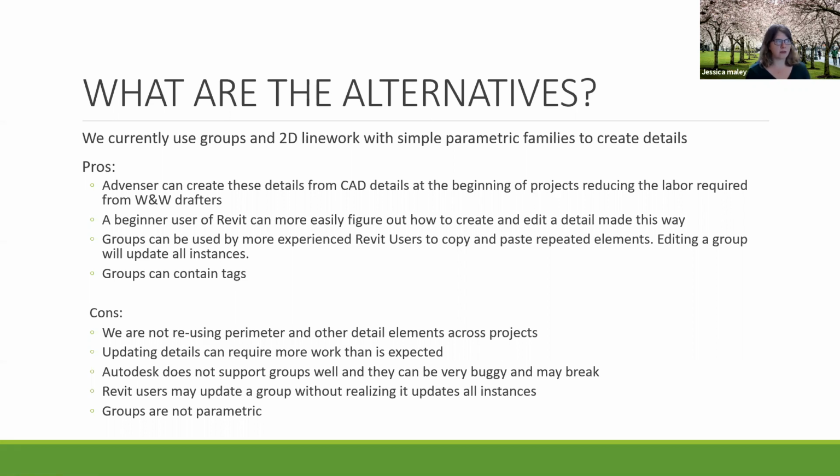They're easier for a beginner to figure out how to create and edit. And more experienced Revit users can use groups to copy and paste repeated elements, and then they can edit those groups to update all instances. And groups can contain tags, unlike families.